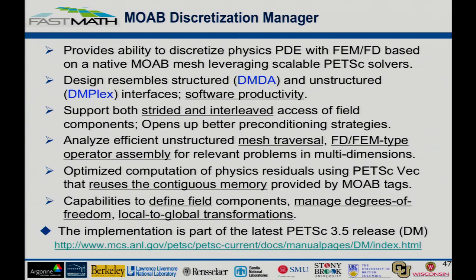So the basic idea is that the DM MOAB interface, or more generally DM, wants to provide the ability to make it easier to discretize your partial differential equation using different types of finite element method and finite difference methods. So the actual design for DM MOAB also closely represents the structured DMDA and the unstructured DMplex interfaces that are in place already in PETSc.